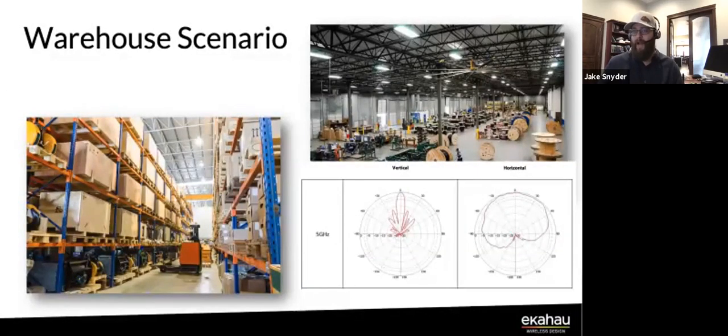And as you ratchet out further and further, it's going to drop off quicker. But knowing that some antennas have a really sharp drop off and some have a very gradual drop off, that's where looking at the antenna patterns comes in. You can see that the pattern doesn't stop at 60; there's still a line. It doesn't shrink back to the center like the one on the left. So even though I'm using a 60 and that 60 at 40 feet is going to be X feet wide, you're still going to get signal well beyond that that's going to be usable.